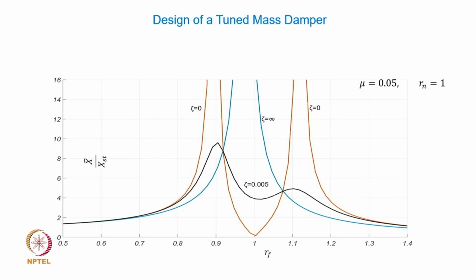For example, API standards for the design of pumps tell you that your quality factor should be less than 8 or so. Preferably, if it is close to 5, perfect. So in general, if you design it to lie between 3 to 8 or maybe 6 or 7, in this range, this quality factor is perfectly okay. The moment this quality factor goes beyond 8 or 10, your design is not really good. You have to rework on your design.